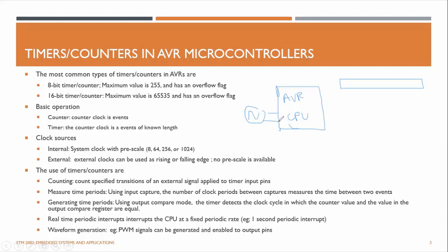So it generates a fixed frequency. If it is a 1 megahertz clock source available to the CPU, right? So this clock pulse, it takes about 1 microsecond for one complete clock cycle, right? From here to here. So now, we can use this to count some time.